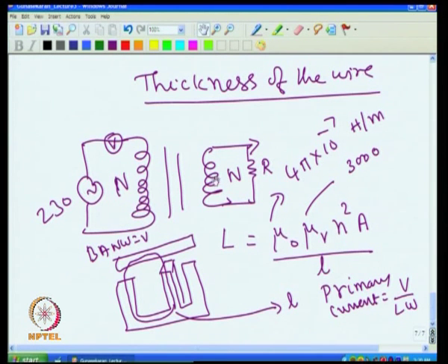Now, because of the secondary current, a magnetic field is generated, and this magnetic field is opposite to the primary one. So it cancels the primary magnetic field, and the net result is a reduced magnetic field. Then again more current tries to flow through the primary, and the more current flowing produces more induced voltage, which is always trying to match the applied voltage.